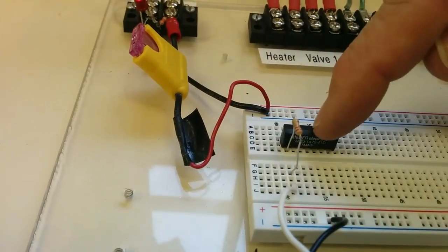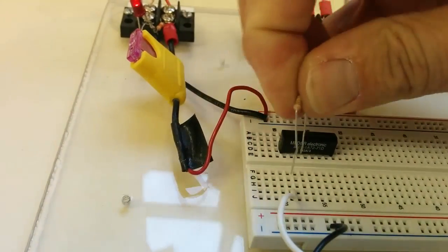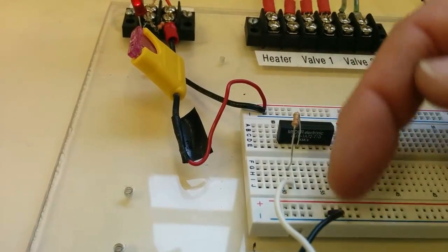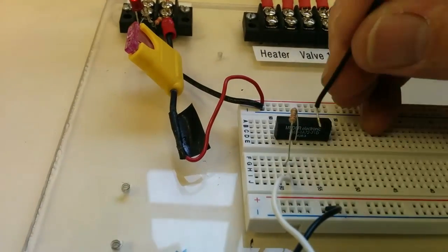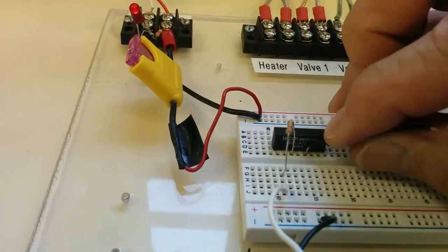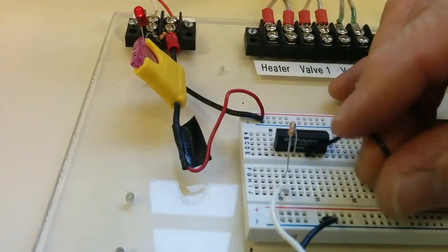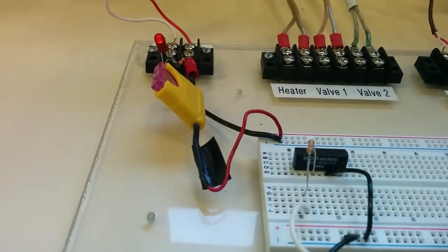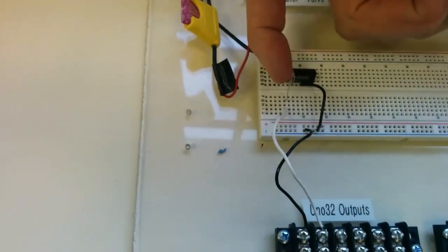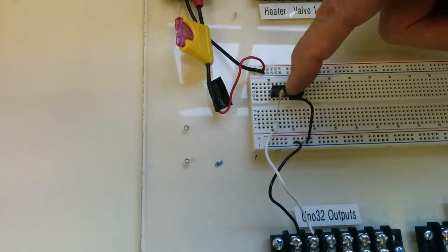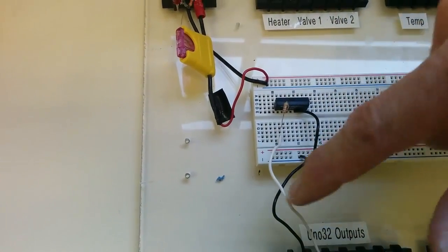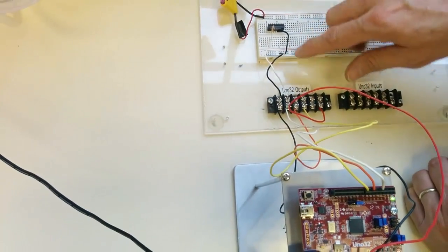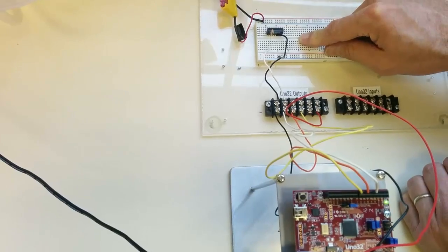Now, that gets us into the relay. Now we have to come into not pin 1, pin 3, because that's where the coil is. So we're going into the coil, and we need to come out of the coil to ground. So the other pin is pin 5, which is the third one over, and we'll bring it back to ground. So again, we're coming out with the digital input, through the resistor, through the coil inside the relay, and then back to ground. So that represents the primary circuit coming from the UNO 32 around and activating the relay.